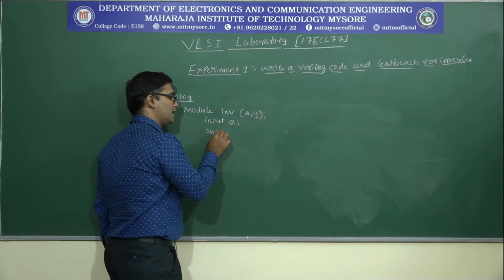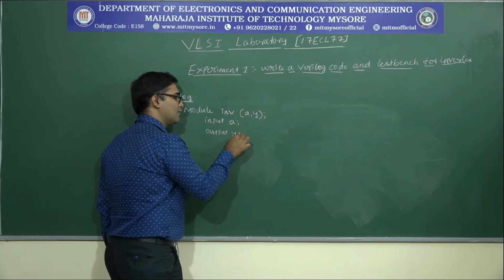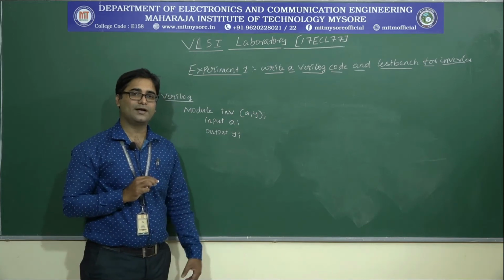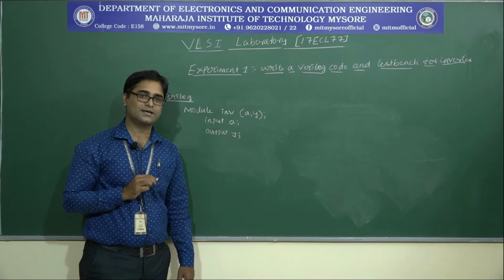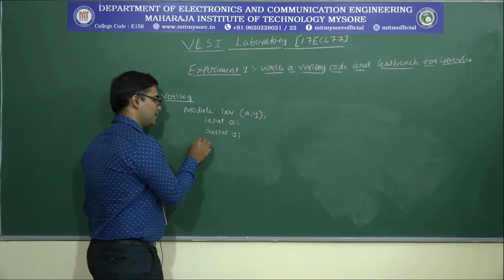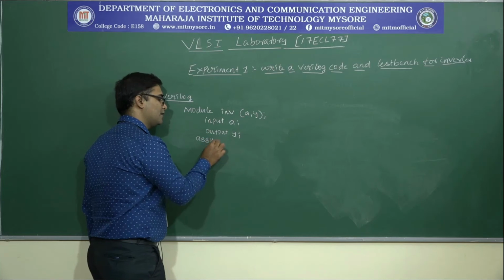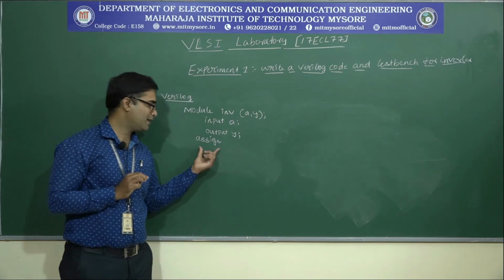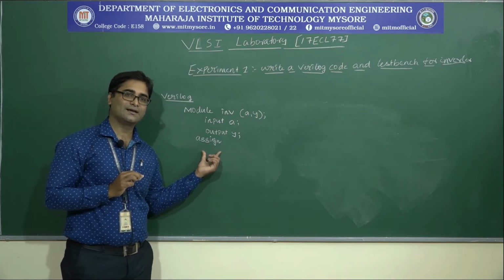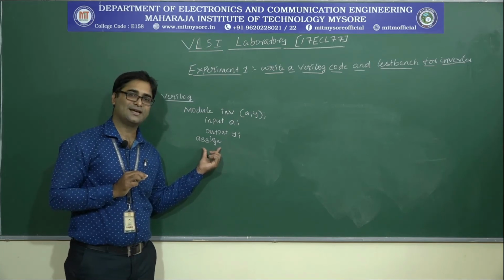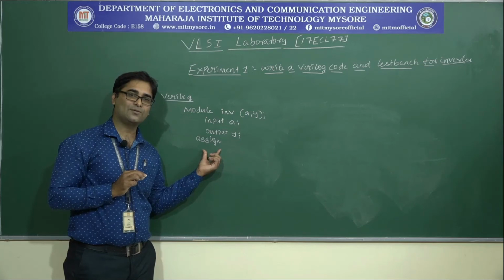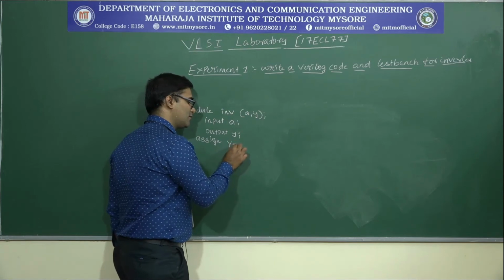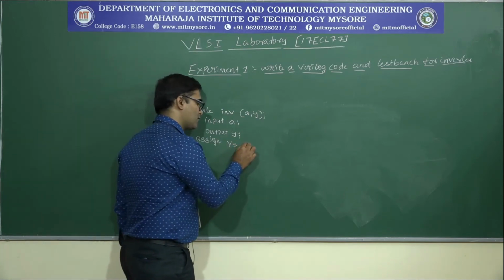and the output as Y. We have said that the inverter is a NOT gate, or a complementary metal oxide semiconductor, where we have a complementary function, which is followed by a particular instruction in HDL called assign, which means it is a continuous assignment statement which defines the value on a net, and Y is equal to tilde.